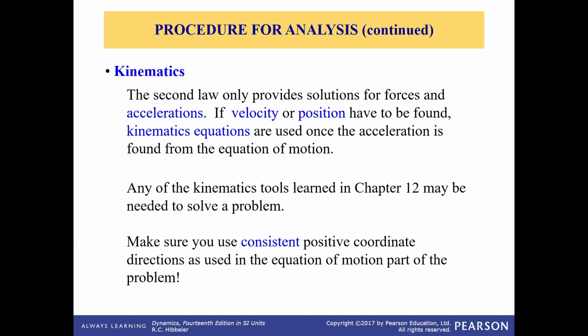Any of the kinematic tools learned in chapter 12 may be needed to solve a problem. Make sure you use consistent positive coordinate directions as used in the equation of motion part of the problem. Still remember that if you have a, to get v, if a is given with respect to time, you need to integrate the equation of acceleration with respect to time, and then you will get v with respect to time. If you want to find the position, you need to integrate that one as well. The same, if they give you position with respect to time, you need to differentiate to get the velocity as a function of time, and also differentiate that again to get the acceleration with respect to time. So you need to recall what you have learned in chapter 12.